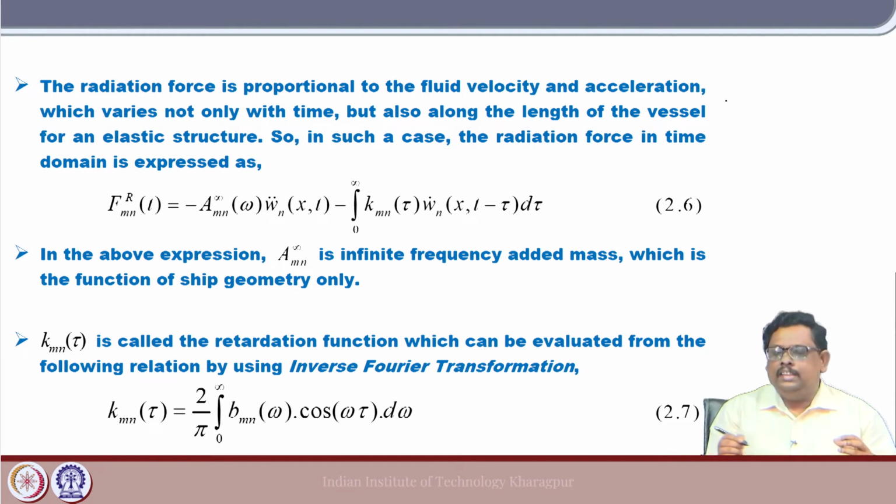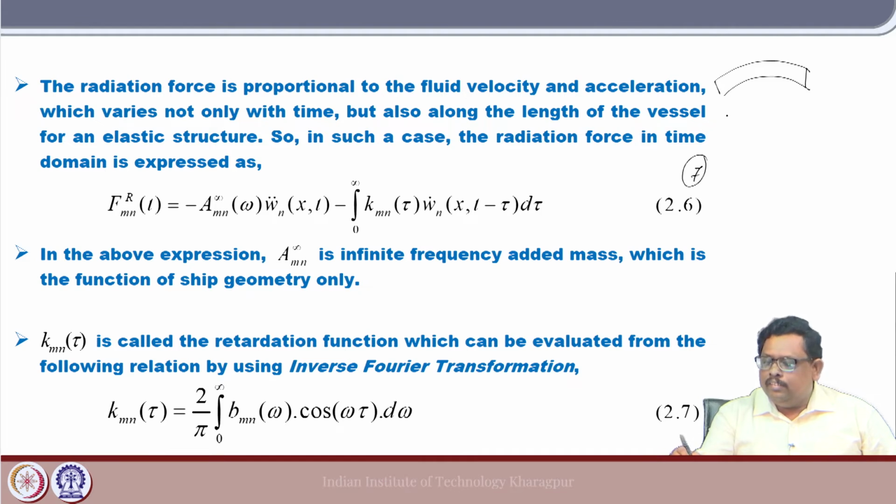Let us say I am using the first flexible mode, which is basically the seventh mode in general. If you consider the first 6 as rigid body modes, the 7th is the first flexible mode. Now, if you oscillate in the seventh mode, how do we oscillate the body? If you remember that picture, you oscillate the body this way.